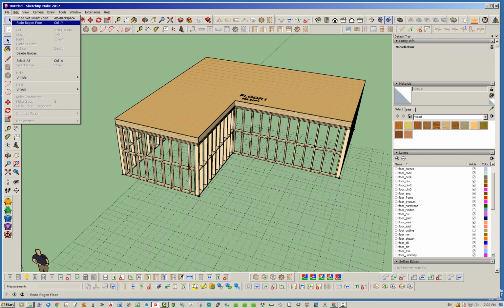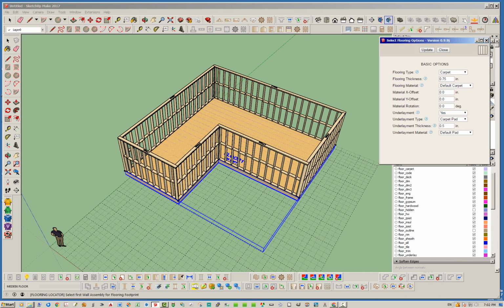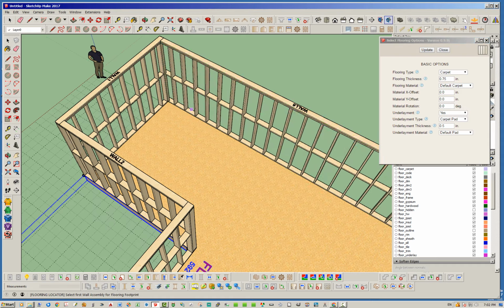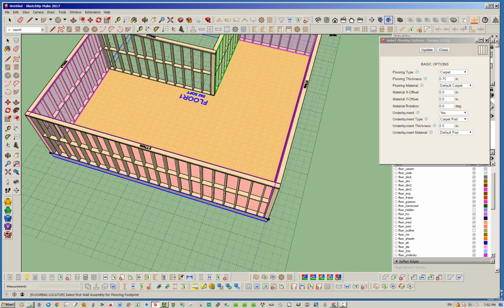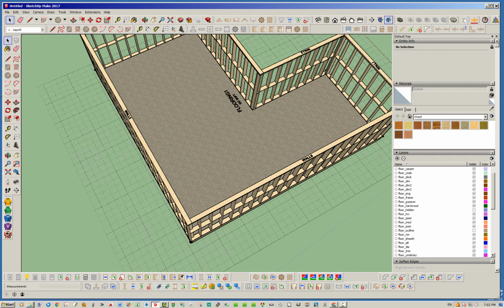So just like the floor covering tool, you can move these walls around. It will adjust accordingly. So I'm going to show you now. I'm going to use the floor covering tool. It's already set to wall mode. I'm going to just throw down a carpet real quick. I think we've got everything we want there. Okay, so now I'm just going to start here. Doesn't matter which way I work myself around here, but I just want to show you guys how quick you can make some edits now, right? So we just select all these walls, throw our carpet down. We could put in openings, all that good stuff.